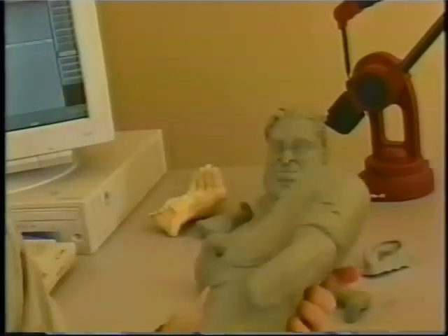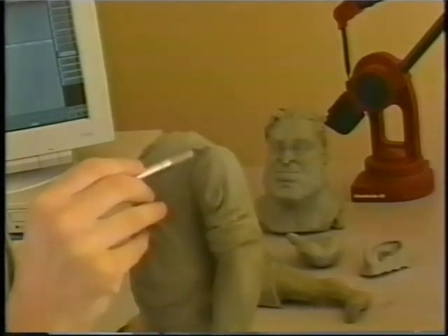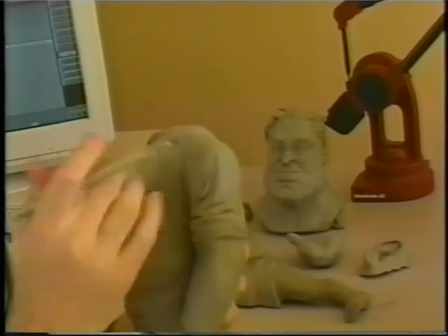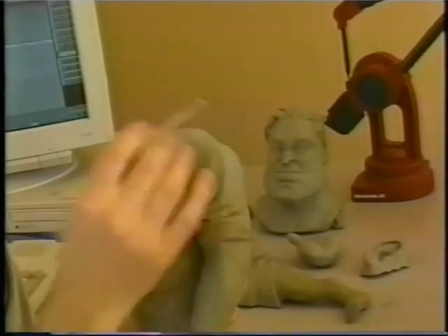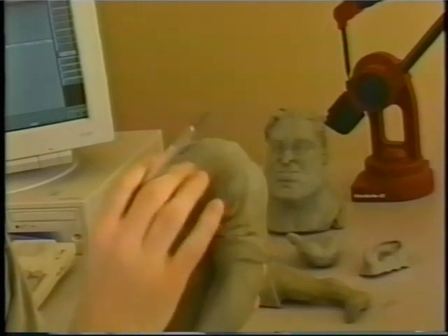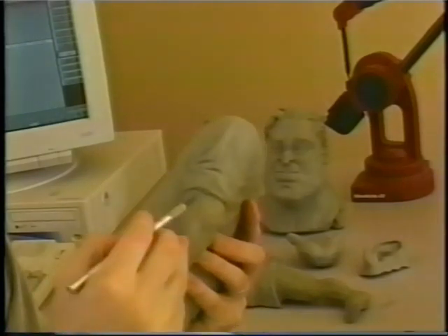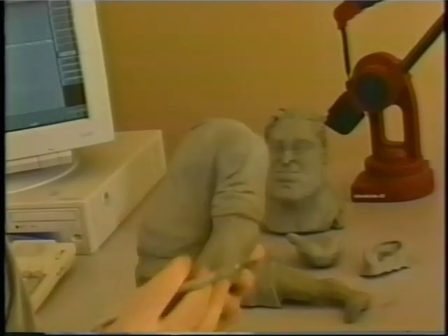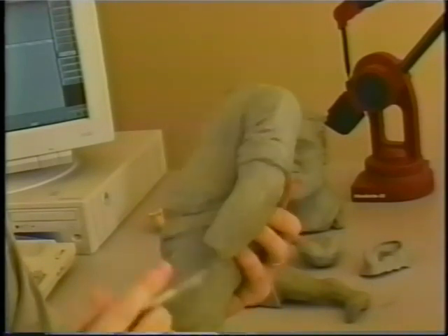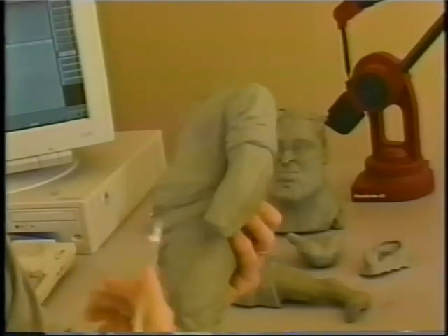So breaks in articles of clothing is one way you can save yourself a lot of hassle. Another thing is breaks in the actual clothing, in the seams of the clothing. So right here there's a seam, and what I've actually done is made a break there so that this front shirt surface continues on underneath this arm surface, and they just come together nicely and make a little bump. And so there's a seam there in reality, and there's also a seam there to make things easier for texture mapping and UV texturing. For the arm here, notice that there's fewer lines going this direction for the arm than in the shirt. And so there needed to be a little bit less detail, so you can get away with that. Same thing down here. The leg went underneath the shirt, so you can have a different surface going this way.